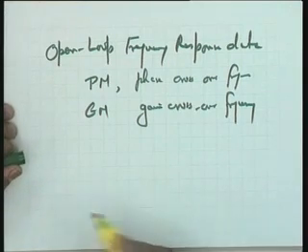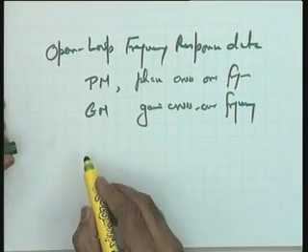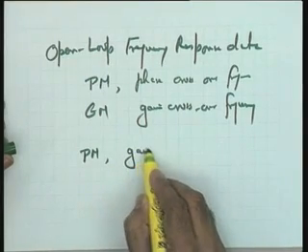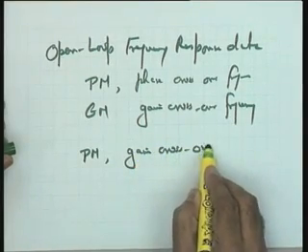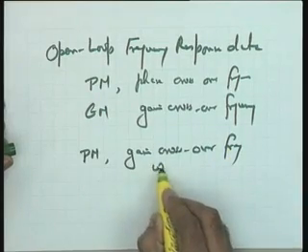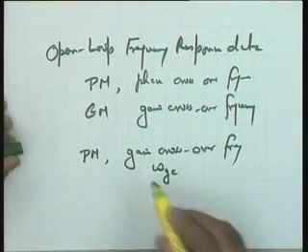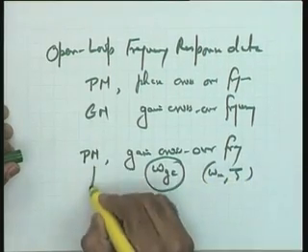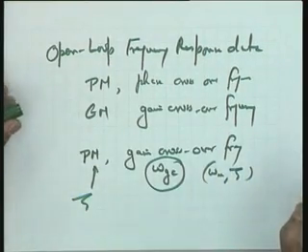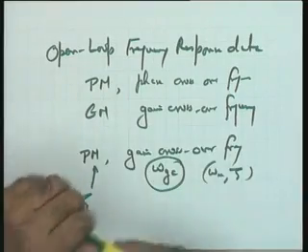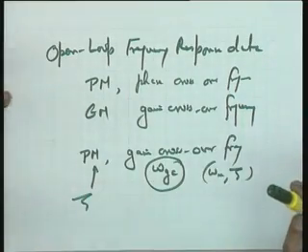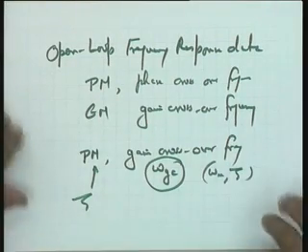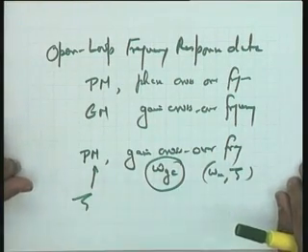We have particularly seen that if we take a standard system, then phase margin and gain crossover frequency are related to zeta and omega n. Let me call this as omega gc. So, this gain crossover is a function of omega n and zeta, and phase margin is a function of zeta, and therefore, if we have the phase margin and the gain margin for a system, we can see the performance, we can visualize the performance in time domain, because the approximate values of zeta and omega n can be obtained